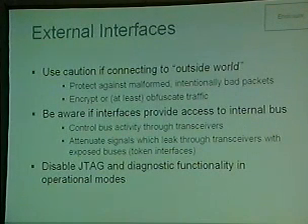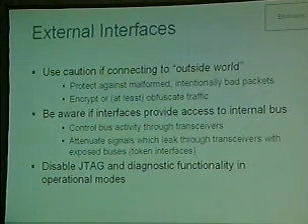Because it's a handheld device and it's kind of like a consumer device, there might not be any security problems there, but if you wanted to use some kind of expansion module in your device, you want to at least be aware of what you're giving people access to. Also, you disable all of your diagnostic functionality, your JTAG, things that would possibly help an attacker probe the device and gain data out of it.